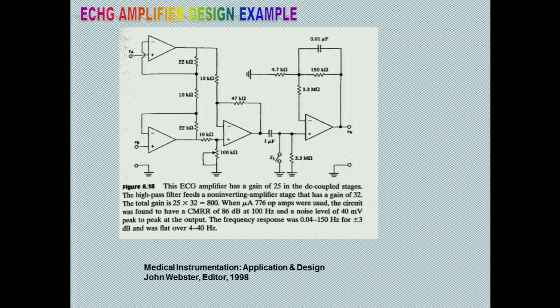Yes, Subir? Forgotten the analog electronics. Losses. Well, what kind of losses? Power loss. Ma'am, if we use a higher resistor, there will be some I squared R losses. What is the current there, what is the voltage? Noise is the main thing, because remember it can pick up anything, so it all will be amplified. So normally you keep the initial one as low as possible, then you will have a higher one.